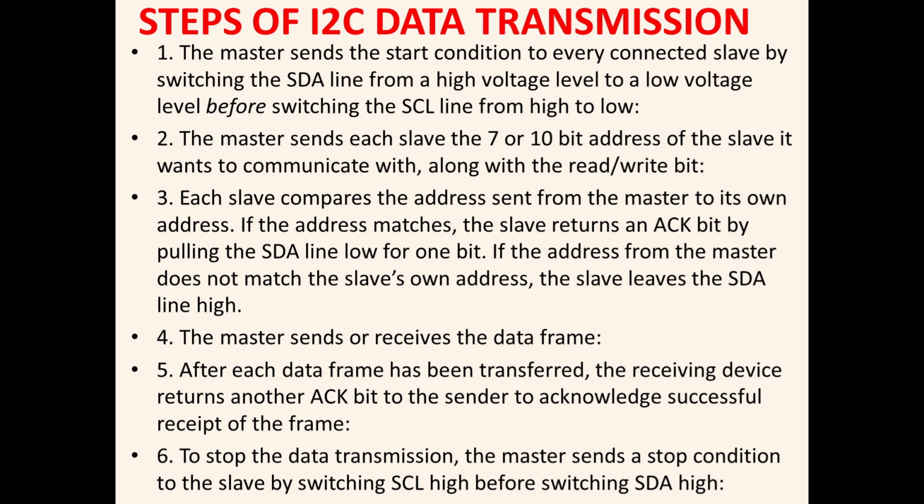After the successful transmission of the whole data frame, there is again a transmission of the stop bit. This stop condition identifies that the transmission is completed successfully, and the end of communication is initiated.